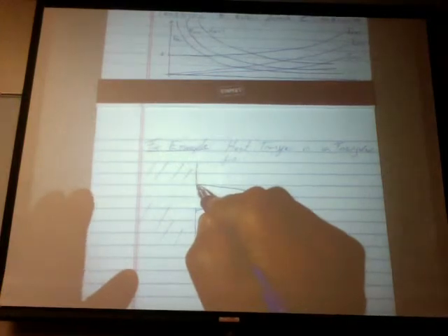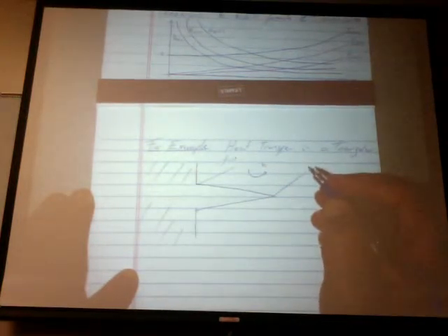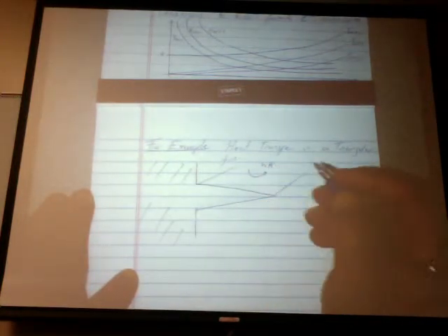Okay? So basically, if we look at this in 3D, this fin is going to have convection on this surface by convection coefficient H, surface area A, T minus T infinity. That's Newton's cooling law, where T infinity is the temperature of the fluid.